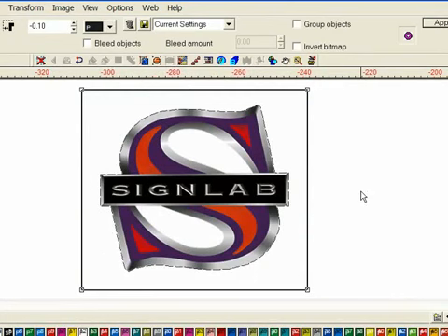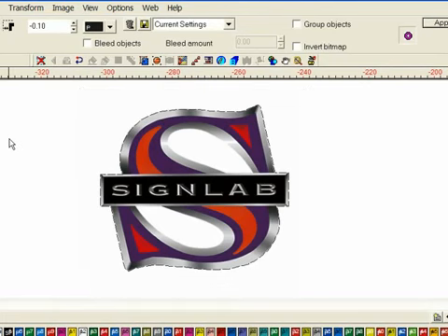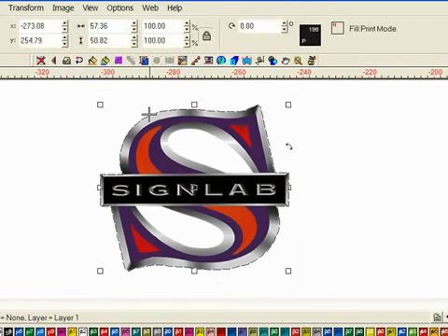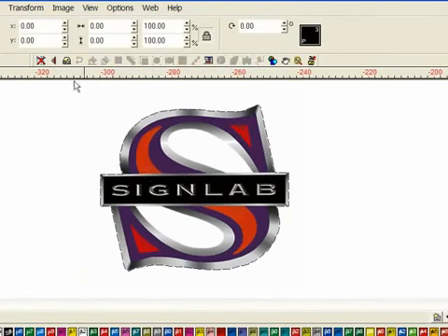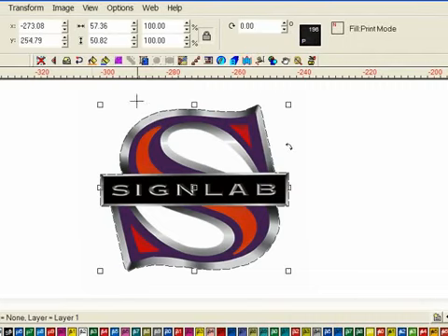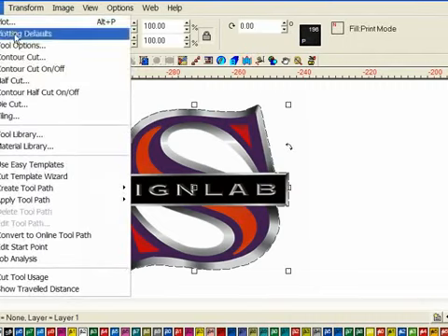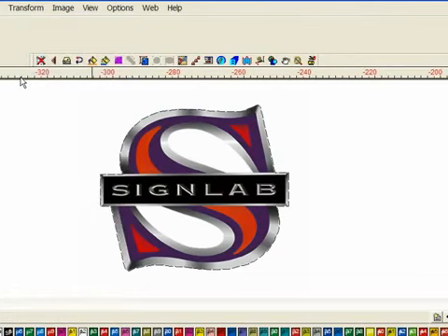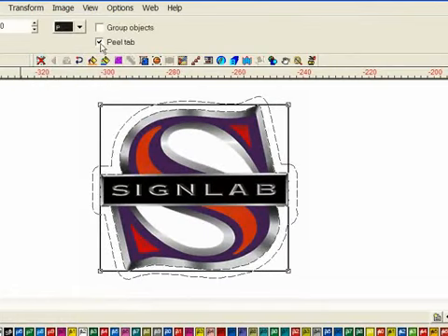The main reason for showing you these functions here is to emphasize that once you have achieved a contour path you are satisfied with, whether that is to a vectored or bitmap object, it's simple to then just select it and apply a half-cut path of the same shape. You can see this in action again as I select the path and go to the Cut menu and select Half Cut. Okay, so once again I'm going to add a Peel tab and my decal is ready for production.